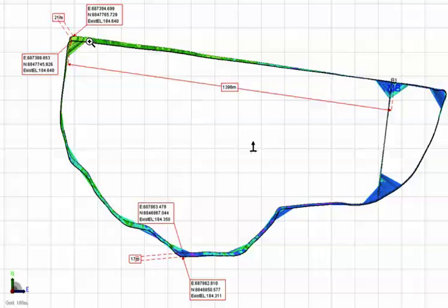Now the difference is that Trimble field level system uses a local plane coordinate system, which is slightly different to the other coordinate system, which is UTM, eastings and northings type thing. So you can see it's 21 meters difference there. And on this southern edge, it's 17 meters difference.